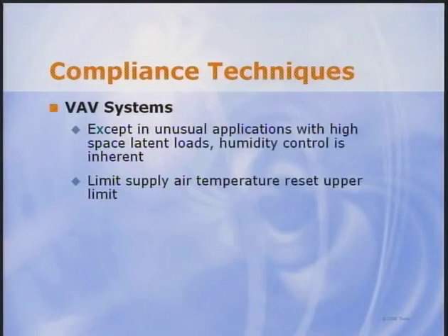Here are a few compliance options designers should consider. First, what about VAV systems? As Dennis showed, for almost all applications, humidity control is inherent with VAV systems. No special features or controls are required. One caveat though, if supply air temperature reset is used based on zone demand for systems in humid climates, make sure the warmest supply air temperature still provides dehumidification at the coil.